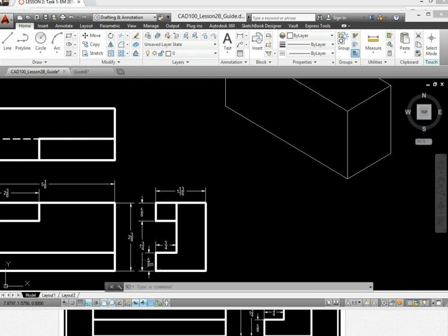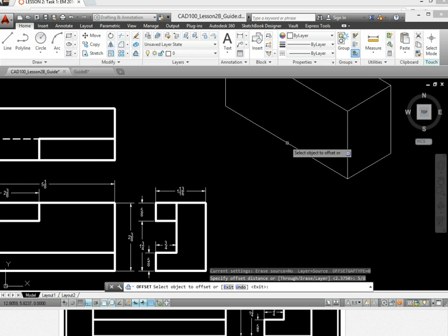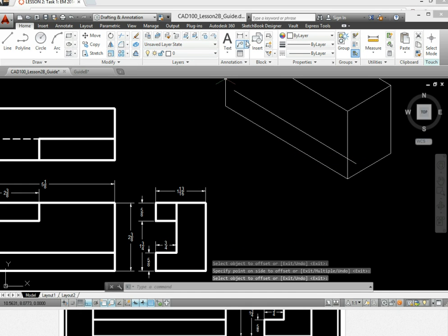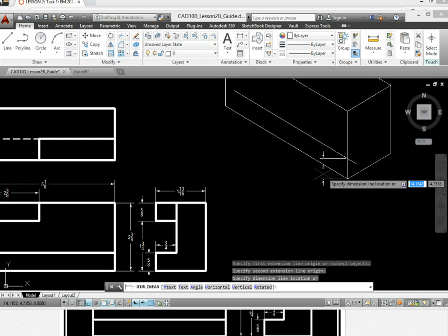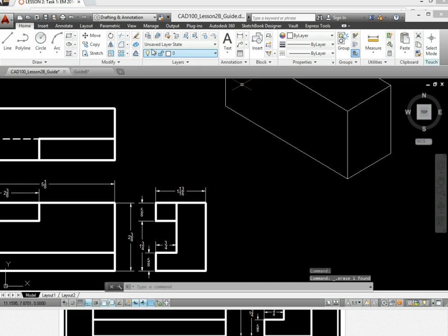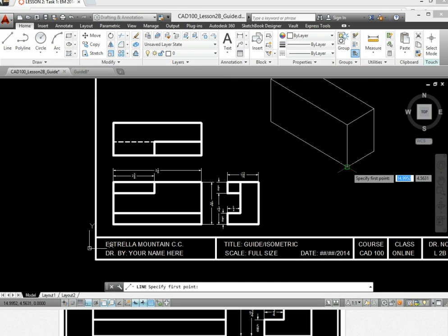It looks like I need to go up 5/8. It's important to know that offset is only applicable in orthographic drawings. In an isometric drawing, if you want to offset this up 5/8, this is what you would see. It offsets up 5/8, as I'll demonstrate here, is not what you would expect. As I measure that height, it says 3/4, which is not 5/8, so no offsetting. Instead, we draw lines along the paths of the perimeter of our block.